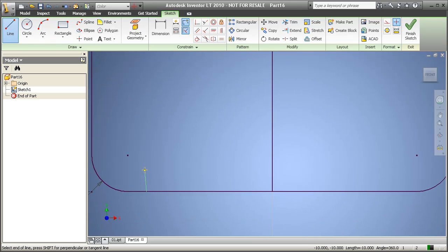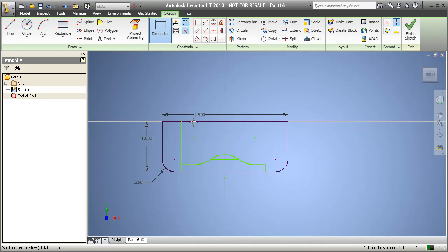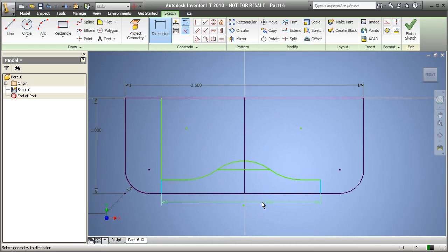After that, we're going to come in here and create some extra geometry for the little squiggly part of that drawer pull. If you hold down your left mouse, you can get it to do arcs, and you'll notice on this arc we can get the bottom of that little quadrant also extending off of that extension of that horizontal line. Add a couple more little lines in here, one more for a coil feature, and then all we have to do is dimension and constrain the geometry to finish it out.